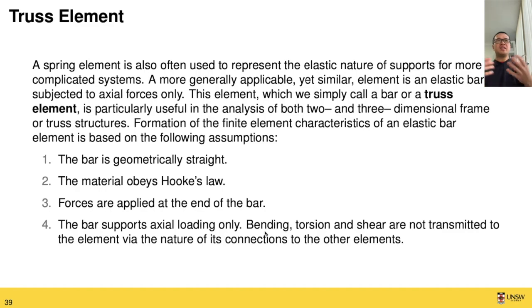There might be more complicated situations where you will have these torsional forces, but for this course and for the truss element, we only consider forces loading in the axial direction. So all the deformation will occur along the axial direction.